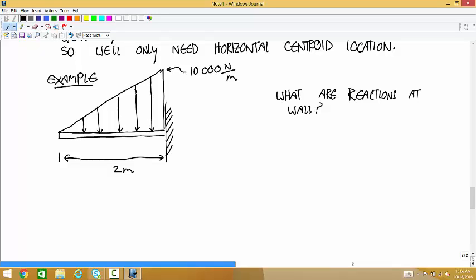I mean, it's probably worth pointing out that really distributed loads are the real things, and point forces are the mathematical simplification. Like if we're trying to figure out what the forces are at this joint here, when I lean down on this, your first calculation would definitely be saying that I'm applying a point force here.